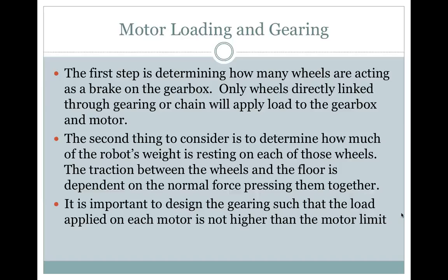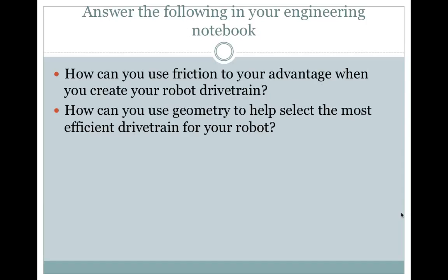The second thing to consider is to determine how much of the robot's weight is resting on each of those wheels. The traction between the wheels and the floor is dependent on the normal force pressing them together. It is important to design the gearing such that the load applied on each motor is not higher than the motor limit. Answer the following in your engineering notebook.